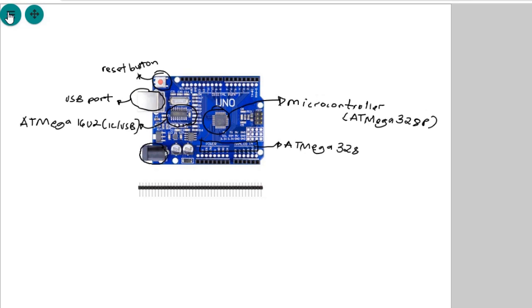This is also a power supply, and it's a 12 volts DC power supply. So in case you have already loaded code on your microcontroller and you do not want to connect your USB port, then you can power this microcontroller board using a 12 volt DC power supply. Now you can achieve that by putting a number of batteries in series, dependent on the voltage of your batteries, to achieve 12 volts DC, and then the 12 volts DC can be used to power the board without necessarily having to hook it on to your laptop.